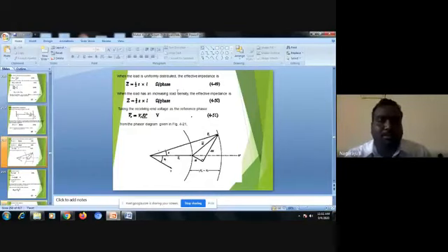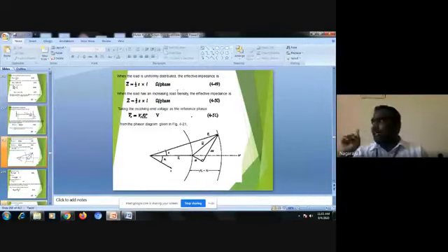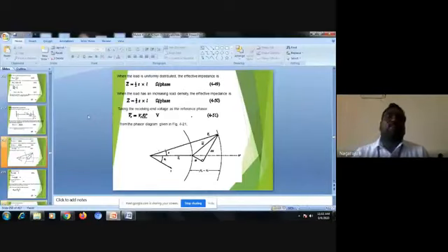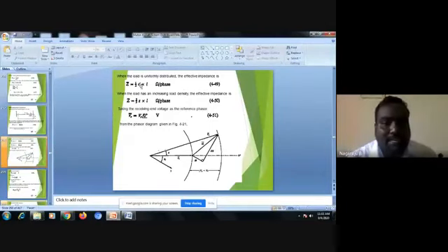You need to know about another two things. At the receiving end side, some may have uniformly distributed loads, and some may have non-uniformly distributed loads connected. So for that the impedance value may change. These two are the important things. Z bar for the uniformly distributed loads, the total impedance value is half of Z into L. This is measured in ohm per phase.